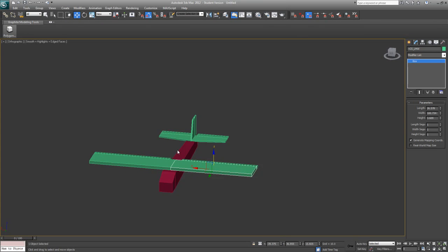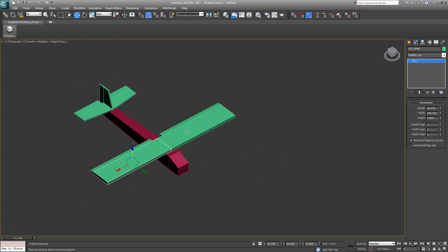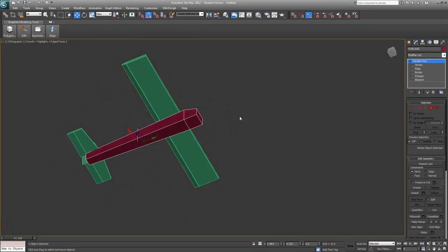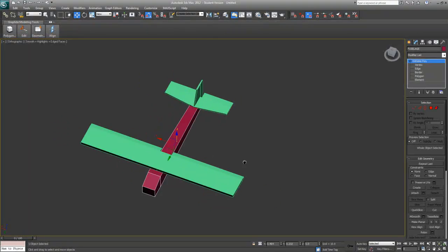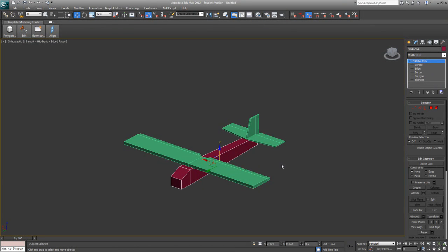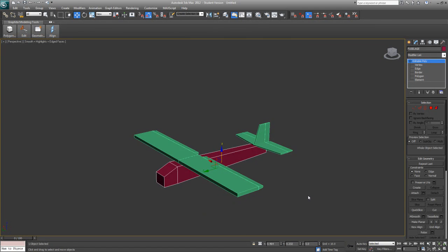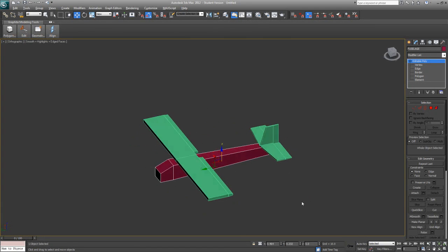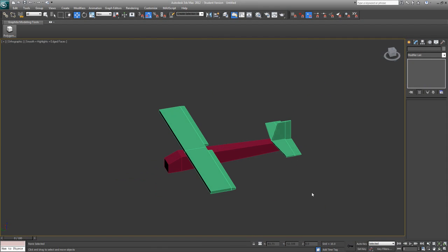See, it's just the oddest thing. Sometimes it works, sometimes it doesn't. You can see, though, it's rotating around the selected part. You select a new part, middle mouse wheel, and Alt, and move the mouse, and you're going to rotate around that part. You can see as you switch, usually when you switch in between, maybe that's when everything's deselected.